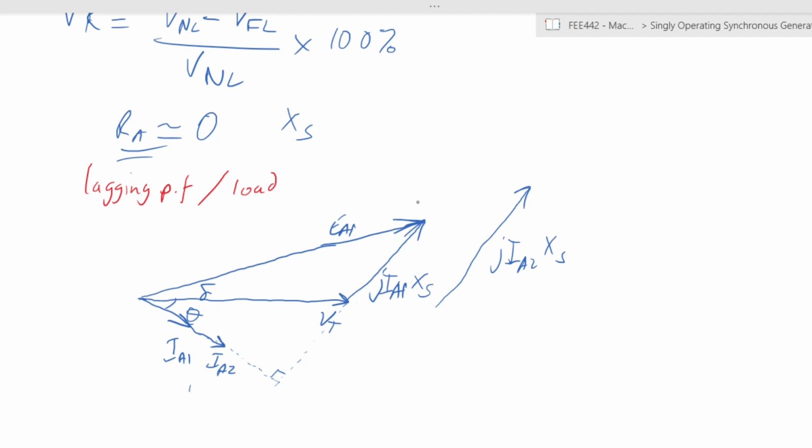So what then happens is, of course, it has to be connected to the terminal voltage. So what happens in that particular case? Now, your terminal voltage, whereas we have been saying it will remain constant, may not be able to remain constant. Why is that? Because this instantaneous increase in the load supplied happens in such a way that you are not able to change the field current, right? So for this case, your load has suddenly increased, but IF remains constant.